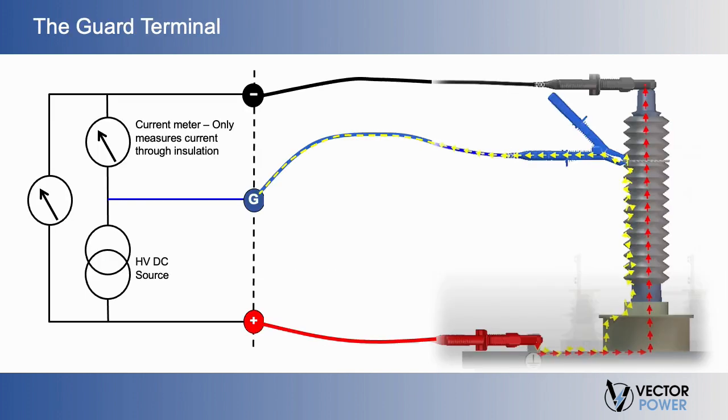Some insulation testers have 2 terminals, while others have 3. As these are DC testers, 2 terminals are the positive and negative. The third, if present, is a guard. It does not have to be used, and many operators use insulation testers satisfactorily without ever employing the guard terminal. However, it affords the operator an extra function for diagnosing equipment problems.